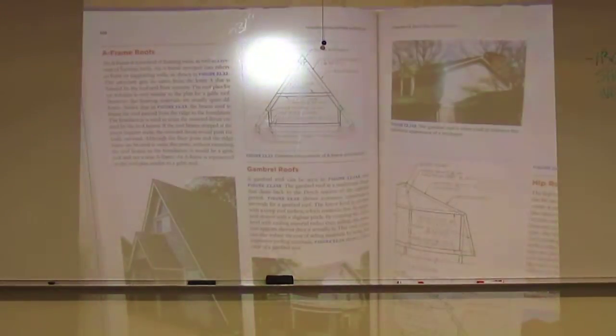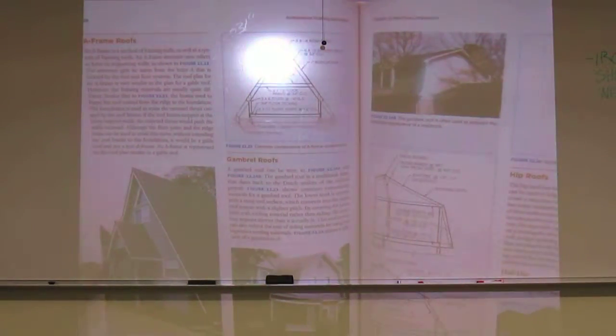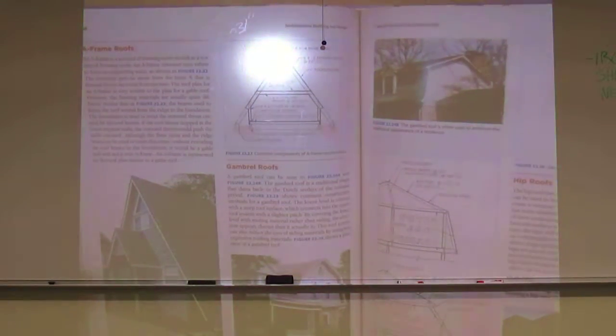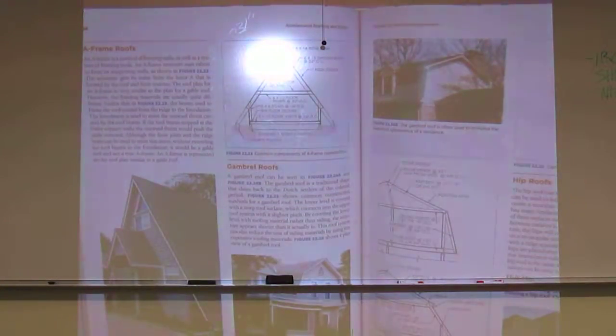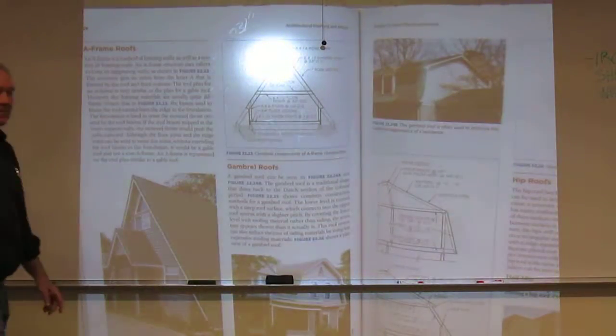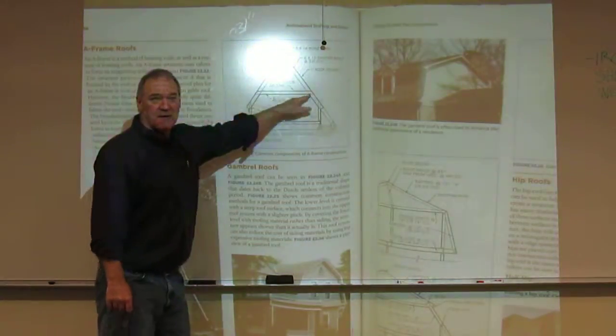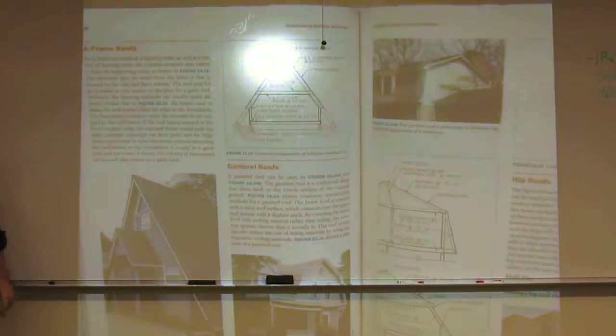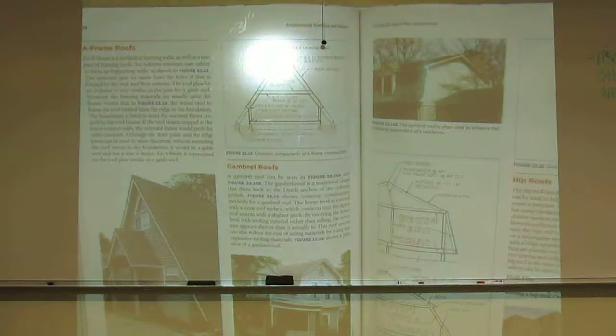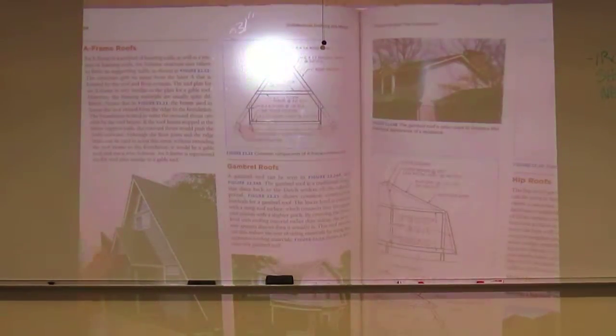They do give you a good section view right here in 22, 23. Generally, they don't have to be, but most of the time they will be multi-floored because we do have to have a mid-span here just to hold it. We're not going to trust just gravity to hold it together. So that's an A-frame. It looks just like a gable when you draw it from the top view.